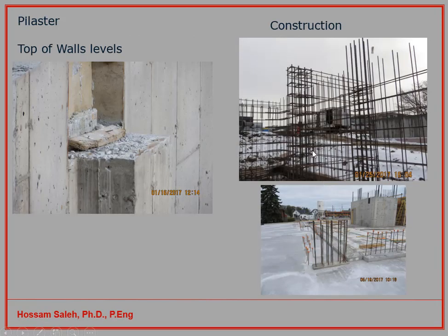And here you can continue and get your cage, or you can have the reinforcing bars, and you can see you can get embedded columns within the wall itself. As you can see here, you have the stirrups and different additional ties within the column. And here you have the dowels, the bars which are coming from one column, and another column will be placed above that. So you need to have an overlapping length between this bar and the additional reinforcing bars for the second level.